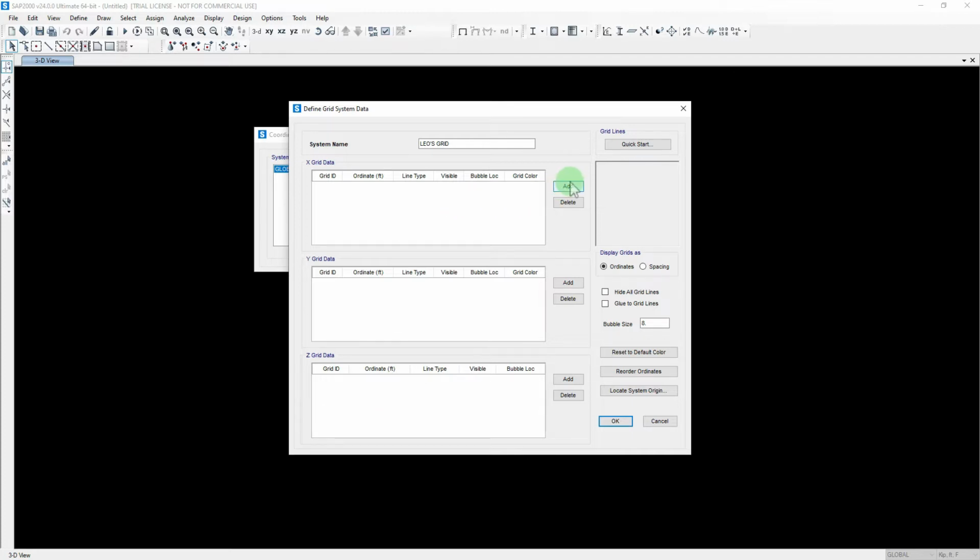So I can add an X coordinate by selecting add another one, and we'll put this X coordinate at, let's go at 5 feet. And even though I'm creating a cantilever column model, for some reason or another with SAP, you have to add several coordinate systems, at least two almost, in order to get them to appear on the screen. I'll demonstrate what that means in a second.